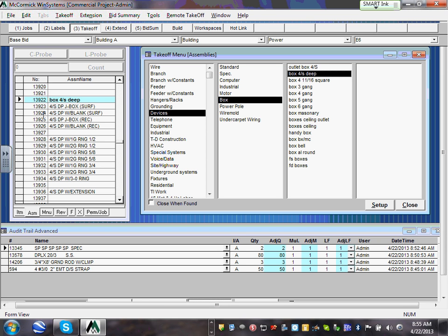So, any comments, guys? Any questions about this project? So we're going to have to measure, find where the box is going to be, and then measure to all the lights. Yes. My expectation with the takeoff, guys, is when you do the takeoff, you're going to line up all your conduits in the floor plate in the power and lighting.